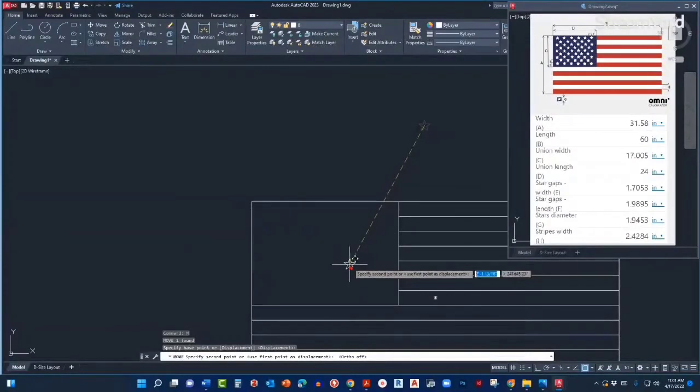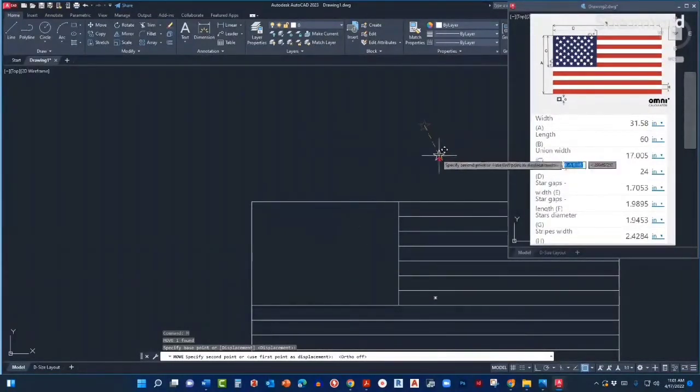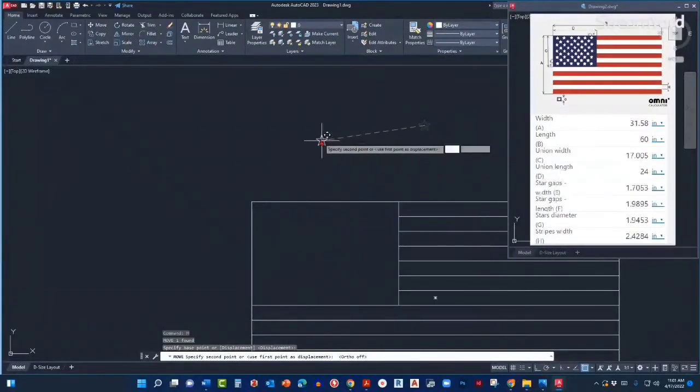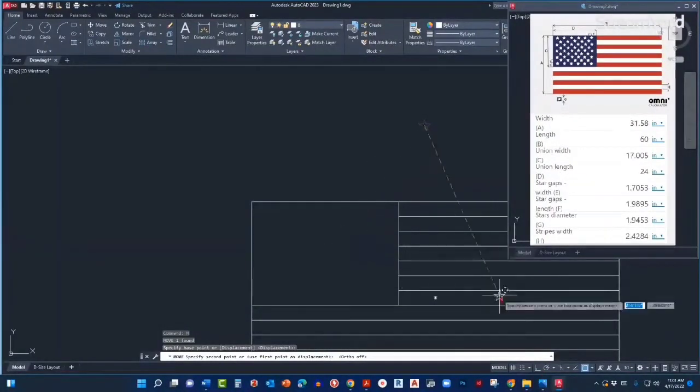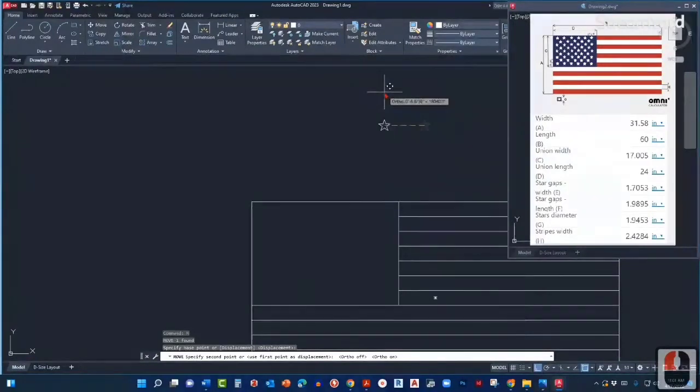Now, that means you have to every time turn on and off the ortho mode to move things? No, not really. Let me show you how. Let's turn it back on again, because ortho is always useful to have on all the time. In order to move freely, we can hold the shift key on our keyboard.